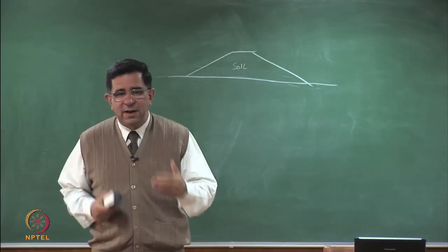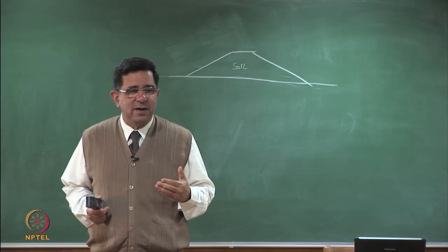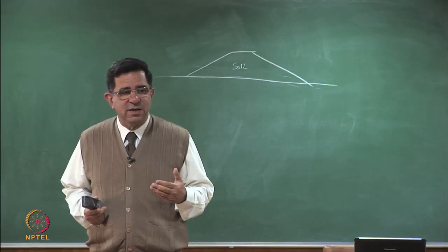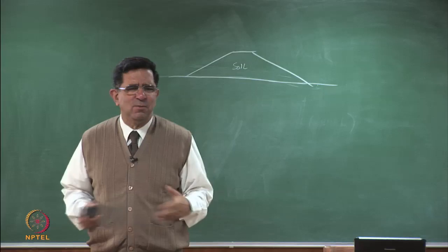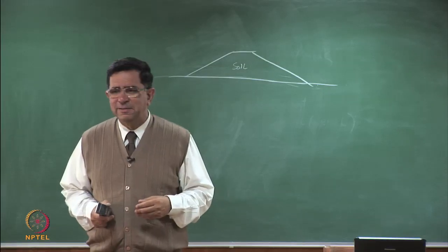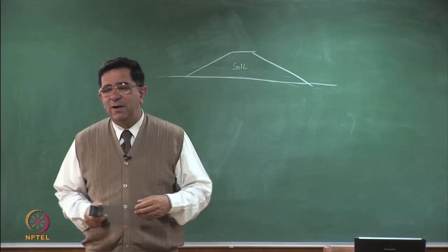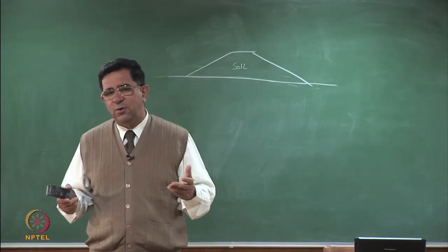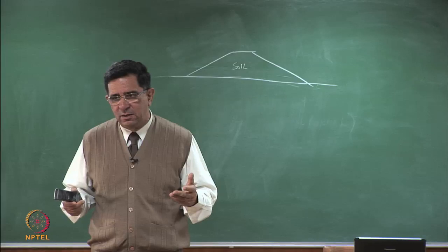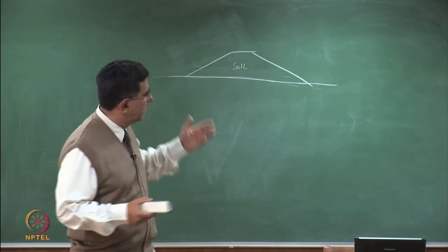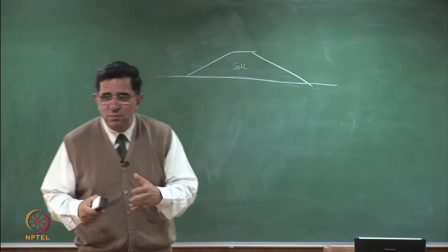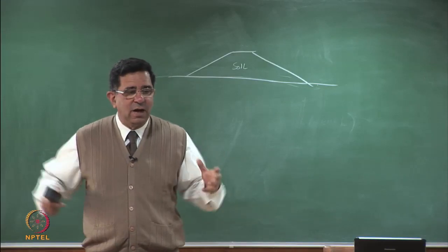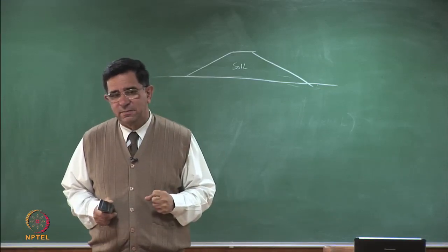Again, let's look at gut feeling. What are the parameters that we are taking out if we are doing drained direct shear tests? What size of the direct shear box would you like to adopt? Well, it depends on the size of the largest particle. When we are doing testing for dams, for rock fill material, when I use the word zone dam, the shell could be made of rock fill. What kind of large size boxes do we need?